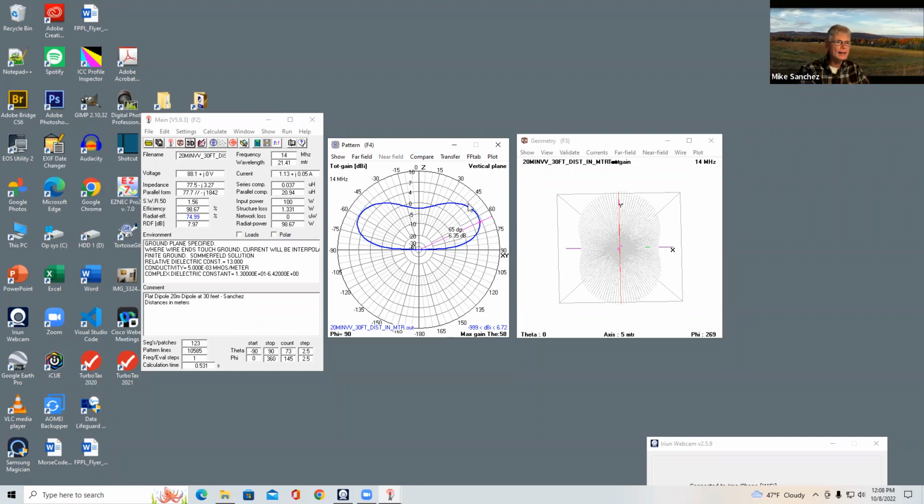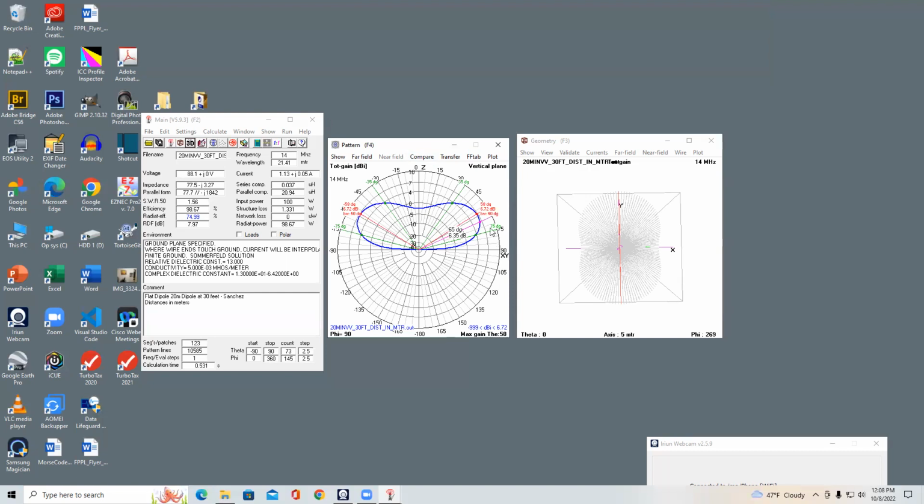Question, press I. Wait, put the mouse focus over this pattern and put this red line straight up at the maximum slice for gain. Okay. Now press I. Okay. Now tell me what it says for the dB in red. 6.65 dB. 6.65.